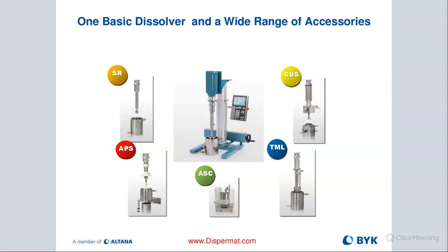We actually recently had an application for battery coating where we were able to really get down the particle size to a really reasonable level just by using a rotor stator. We didn't have to actually mill. So that was really nice to see that we were able to do that also on the same piece of equipment where we usually do the dispersing with.